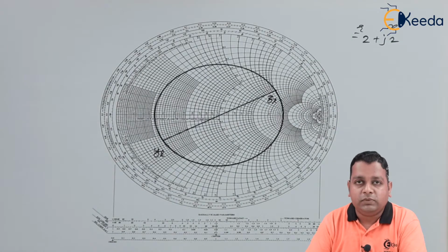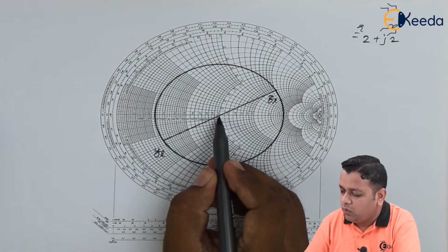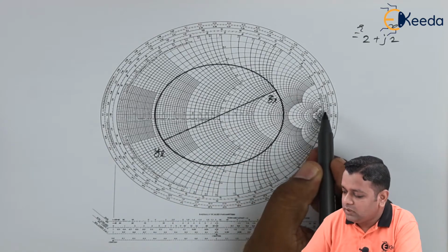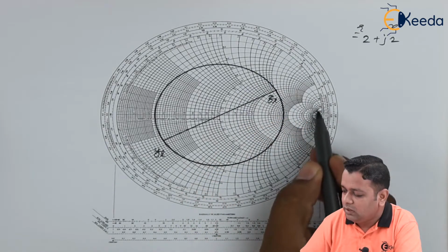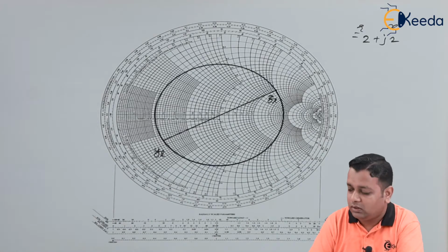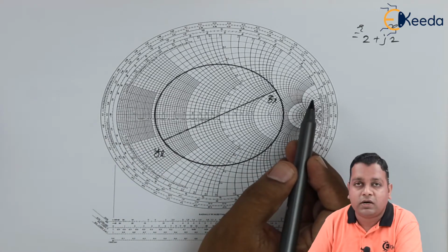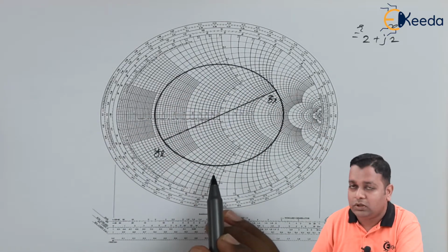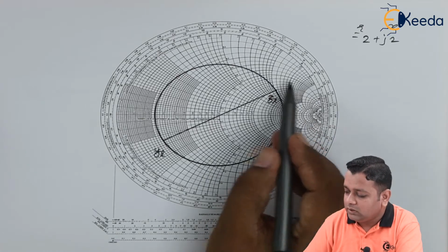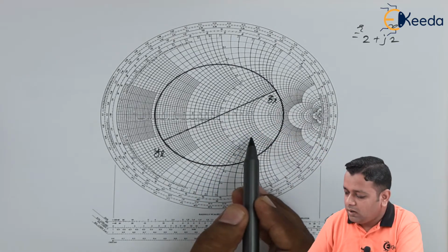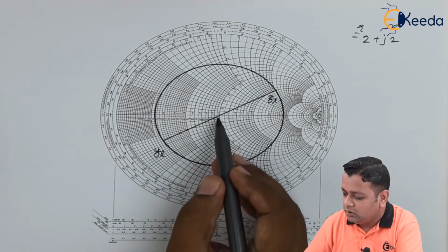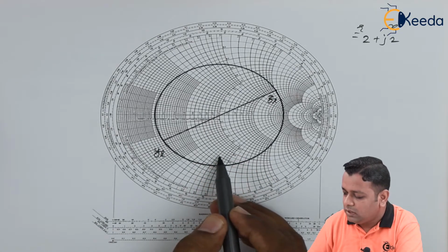Now getting back to the Smith chart here. Here we have the marking of 1.0 at the center of the Smith chart. So right from this place, as we have this particular circle, this will be the g equal to 1 circle, and by making a rotation of 270 degrees, it means we have to go for the third quadrant on this particular scale. We shall be having such a circle located at this particular place. So it will be having a diameter between 1.0 here and 1.0 here. So this will be the diameter and the center will be somewhere here.